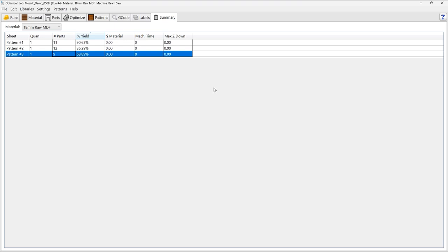So as output file formats, you will get all your nesting labels, you will get all your MPR files or machine CNC files, let's say, all the cutting sizes, all the finish sizes, and you will get your optimized patterns. All the information which is required for machining, you will get from Mozaik.